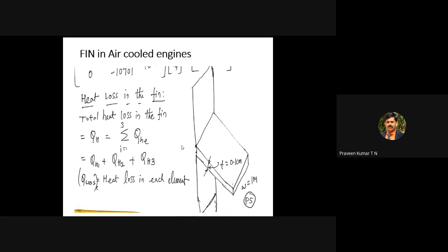Some amount of heat is still there in the engine itself. That amount of heat you have to extract from the engine, so finally it goes to the surrounding medium. Otherwise, the engine temperature increases and it may not perform well. Your piston gets stuck inside the cylinder because as temperature increases there is more expansion, and the clearance between piston and cylinder is very, very small.